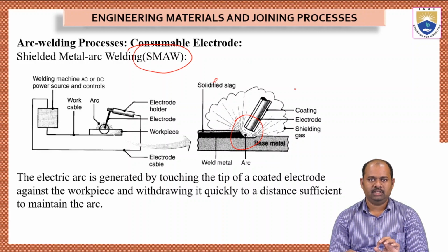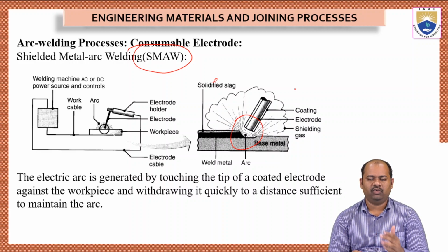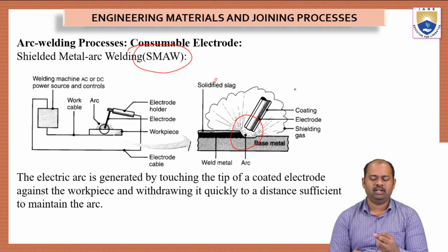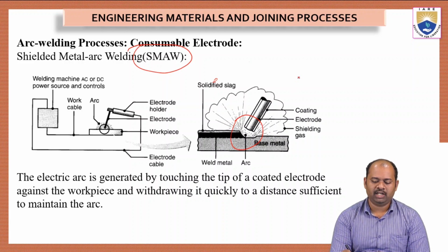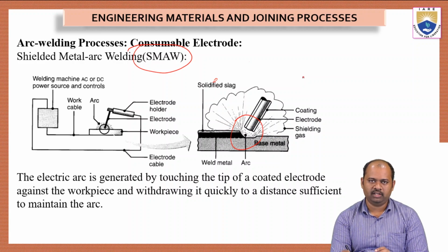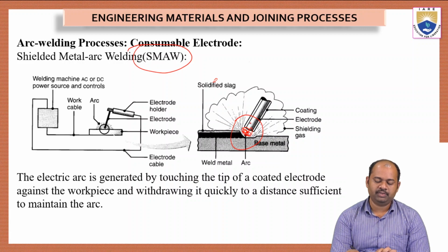This resistance will create a spark. Okay. Generally, if there is any resistance in a body for the flow of electricity, it will form some kind of sparks. Okay. So we are using the same concept in welding. So we have to touch the metal workpiece with the electrode and we have to slightly move it further so that it will form an air resistance in between these two. So here air will be there, it will form some resistance.